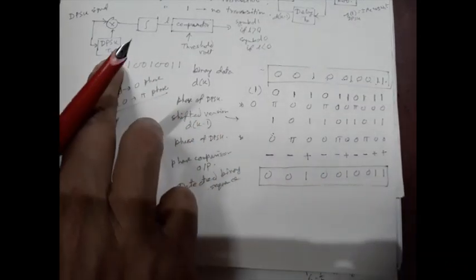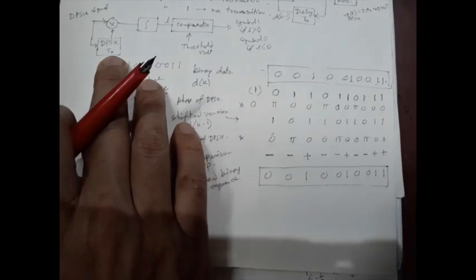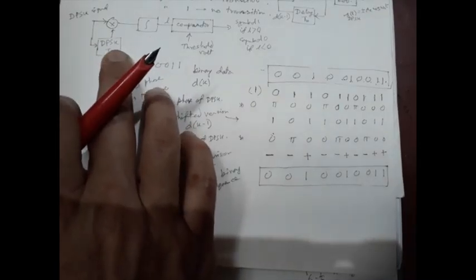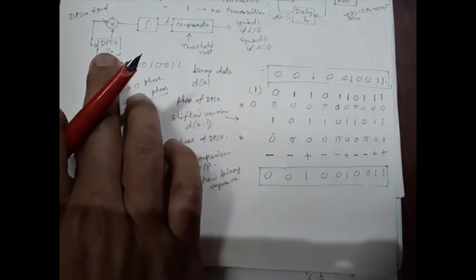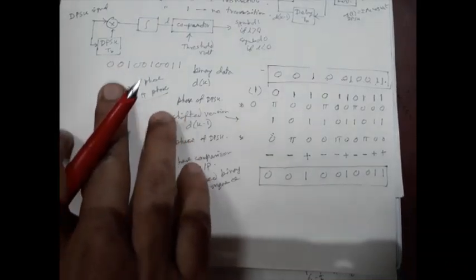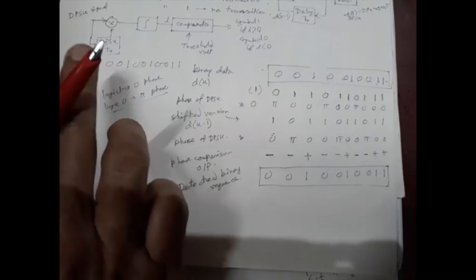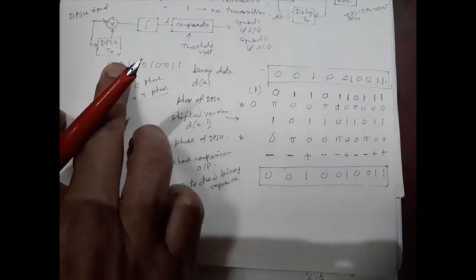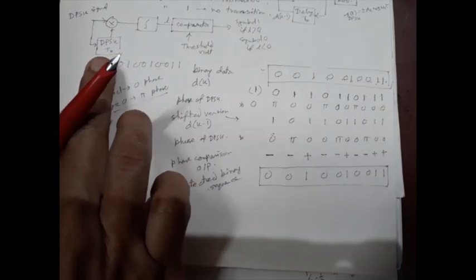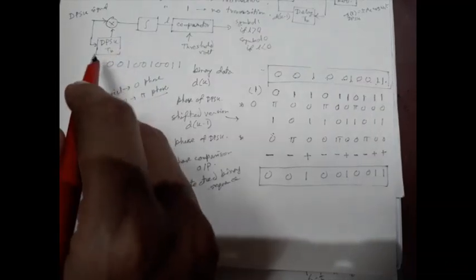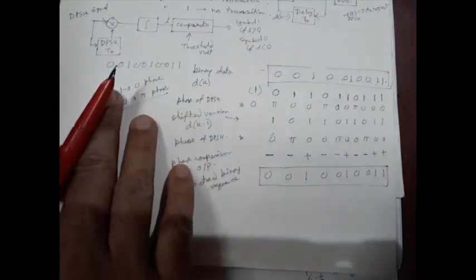Here you can see that this receiver is asynchronous in nature because there is no locally generated carrier. There is no question of phase synchronization. So the problem of synchronous detection of conventional binary PSK is now gone. If we use the differential encoding technique, we can eliminate the need for phase synchronization of the carrier. So this DPSK can be detected in non-synchronous fashion, and that will reduce the cost of the binary PSK receiver system.